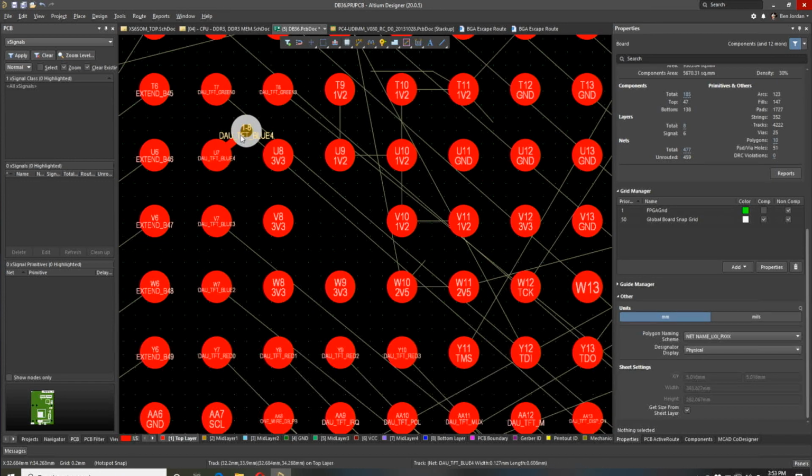You don't have to go spaced between the pads. That's actually a waste of space when you're fanning out. A lot of what you were seeing before, you want to make channels under the device. And now with modern board fabs, we can get via barrels pretty close together safely. So it's good to cluster them up so that you have those channels to get out from under the chip.